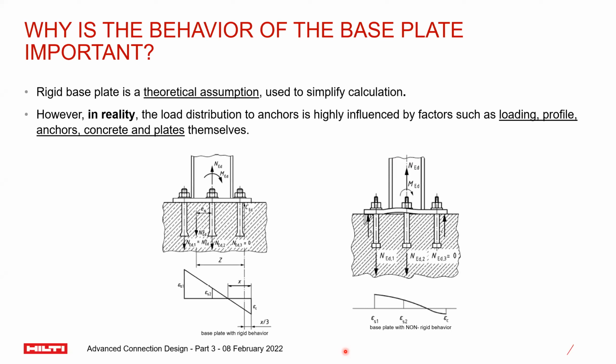The Eurocode 2 methodology based on the rigid assumption, and likewise the AISC Design Guide 1 methodology, is theoretical and generally conservative. It is also code compliant, so that's for sure. However, the behavior of base plates under externally applied loads in reality depends on loading, profile, the concrete type, the material of the plates, and numerous other factors. For this reason, base plates in reality generally don't bend only about fixed bending lines. Bending generally occurs based on the load distribution. So this non-rigid behavior cannot be explained using Eurocode 2-4 or AISC Design Guide 1 based on rigid assumptions. Again, please note that I'm always emphasizing the word assumption, so just keep that in mind. This is where finite element methodology is used to capture the realistic plate behavior.